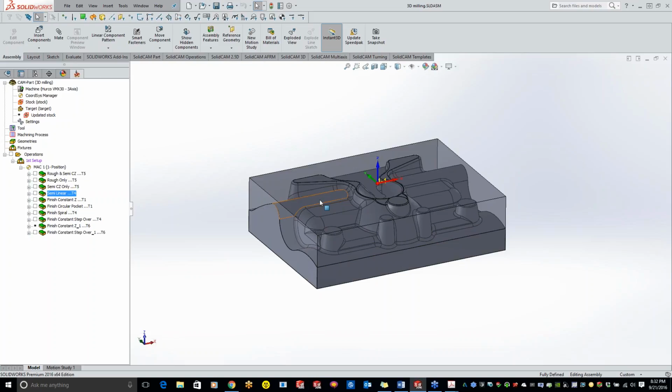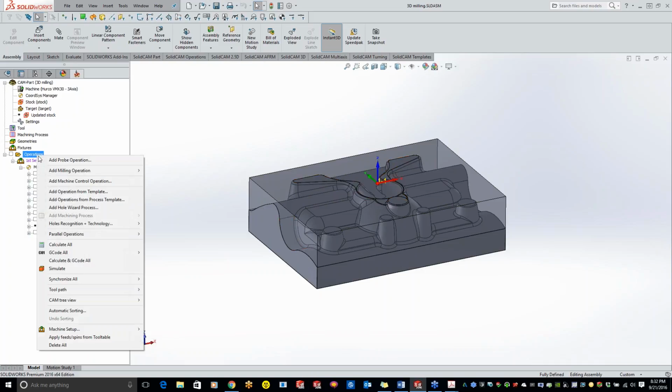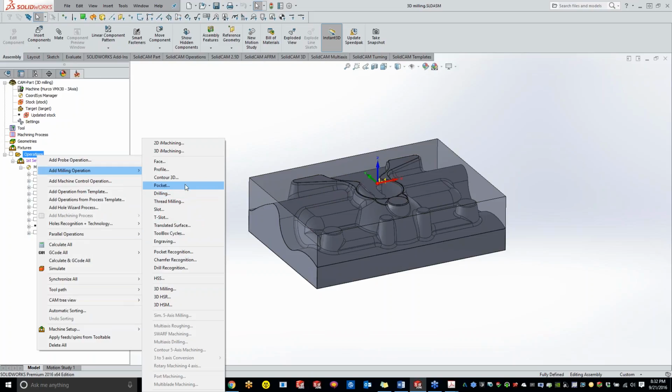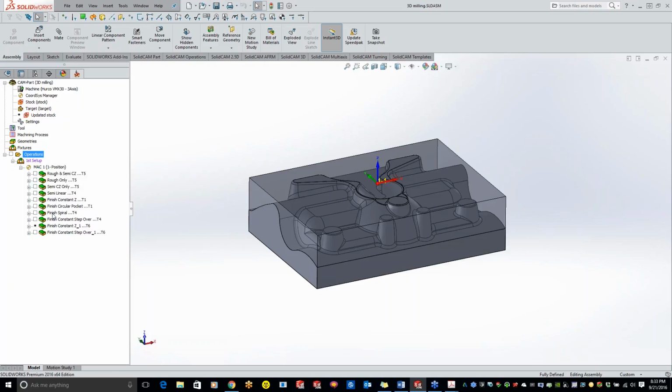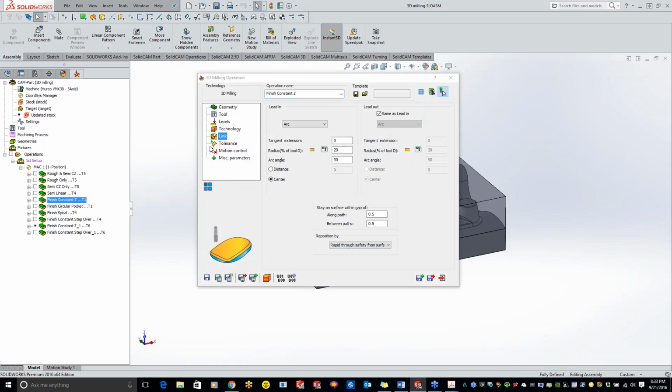Getting that 3D circular pocket, you get a really nice visual with tool lines on there. If a customer is going to see it and wants those nice pretty lines, you can add that in there, where you don't have that option inside the regular pocket operation right here. So like I said, don't look at it as just doing 3D parts only. Definitely take advantage of some of the toolpaths in here to really hog out some material too. So, all right. Thanks, Terry, for that too.